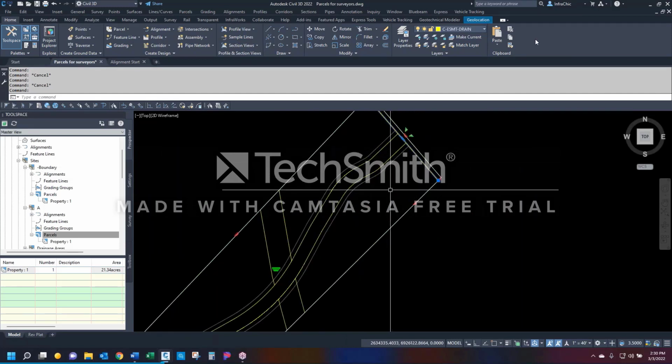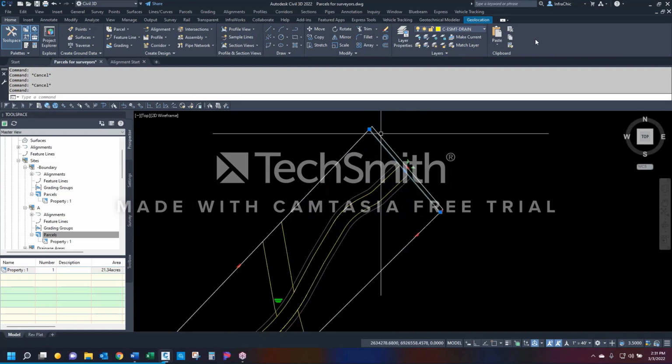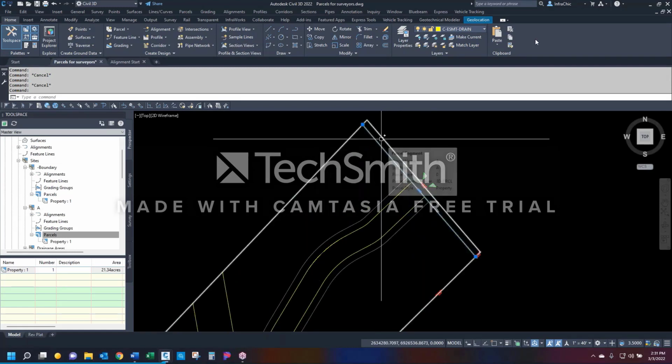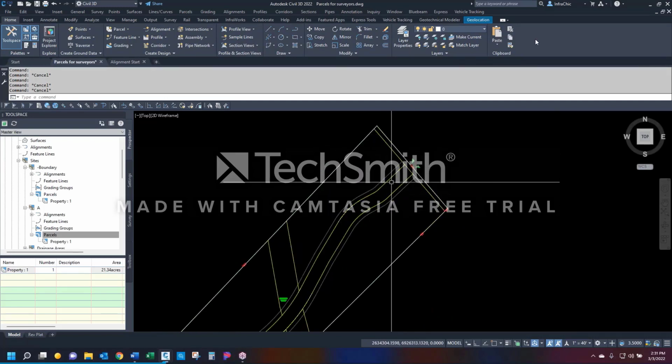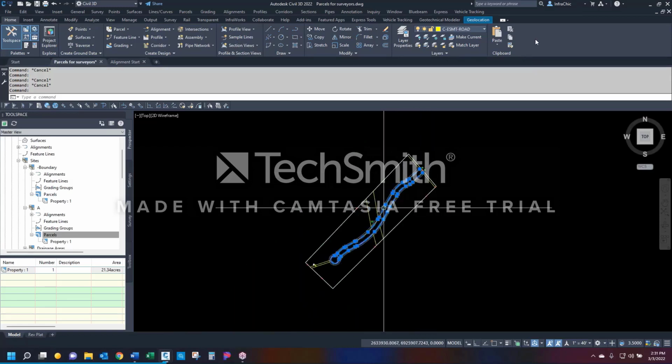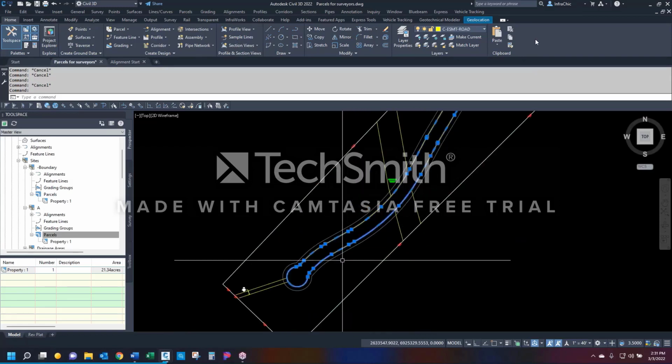Lastly, there's an additional right-of-way up here coming from this main drag over here. This is Farm to Market 987, also known as FM 987 road. So this here is the additional dedicated right-of-way we have to give to that road. That means I have some restrictions before I can begin my plat. I know that's going to be based on the alignment I created some time ago. This is going to become my roadway right-of-way.